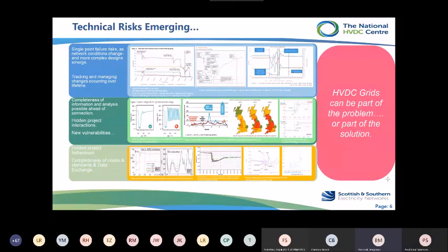A converter is essentially a device with a current rating and not a current overload rating that is appreciable or of long duration. So if you're expecting a device to simultaneously respond to, let's say, a disturbance in both frequency and voltage, then it may struggle to do so. And there are examples in California of solar projects falling out as a result of lightning strikes because there was a simultaneous move away from the frequency bandwidth they were expecting. At the same time, there was a voltage disturbance. And so we've got to be guarded against the overall behaviors and make sure that the robustness of the controls is there. And these controls are very flexible.